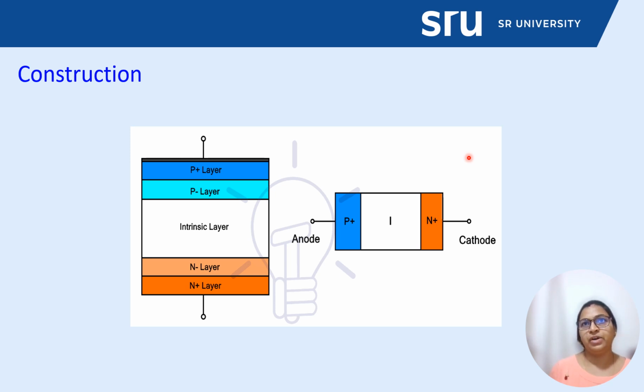high voltage performance. So a PIN diode can be manufactured or constructed in two ways: the mesa structure, which we'll use for low resistance and capacitance, and another where we'll use it for high speed and high voltage performance, we'll go for the planar structure. So this is just the difference between the two ways to make the structure of this diode, depending on the applications.